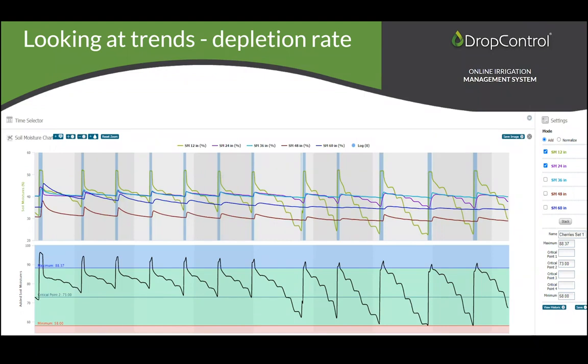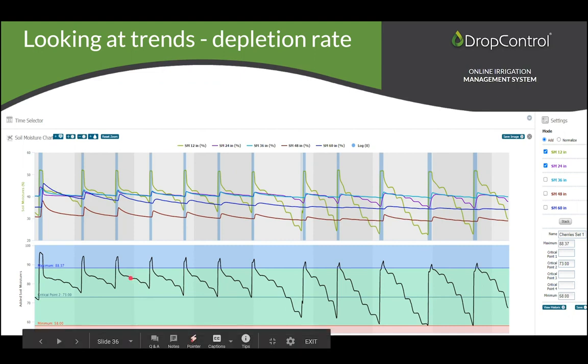That's one of the pros that water potential sensors have, where your scale is the same. Water content sensors have different scales and different numbers for different soil types. What might be a wilting point on a compressed clay could be field capacity on a sandy loam. So we're not looking at the numbers, we're looking at trends. We're looking at depletion rates. Here we can see clearly that in 3 or 4 days, the water got all the way down to half of my tank.